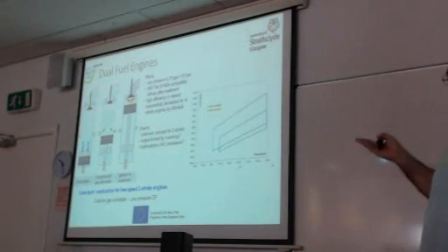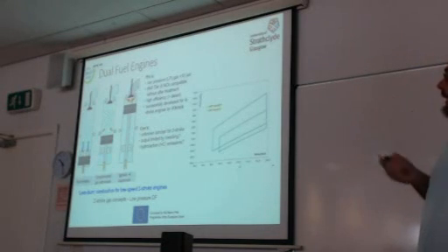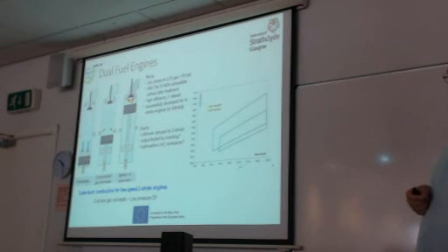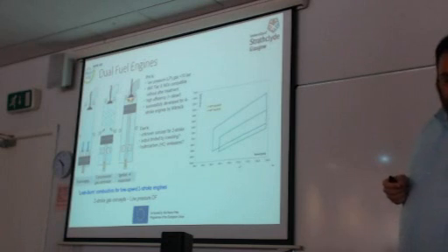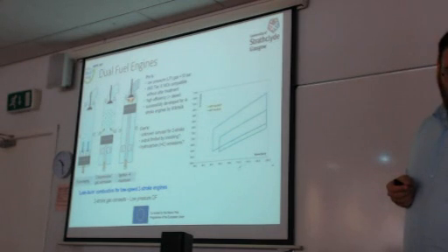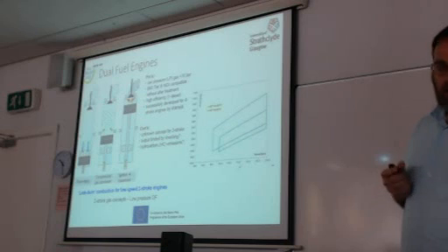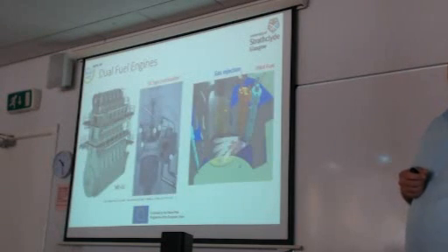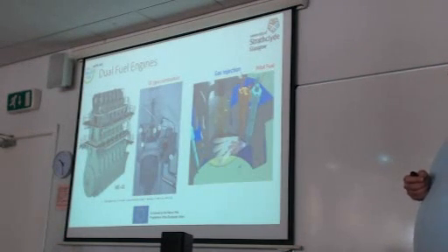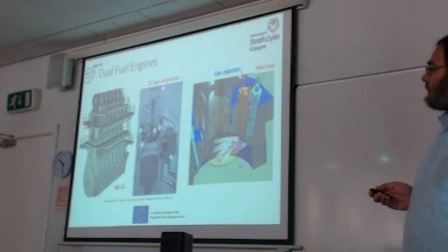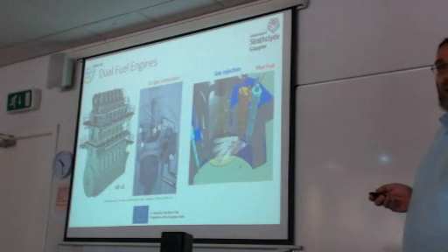Even in the case of a four-stroke diesel engine, in order to be converted into a dual fuel engine, a full conversion package is needed, which contains changing of engine components, injectors, the piping system, the feeding system, and so on and so forth. So it's not just that you have the fuel on board the ship and that's all. So you need, of course, an extensive conversion. Yes, but in this case you have to open holes on the block of the engine, and I suppose that is something complicated. Anyway, if you go to the site of Wärtsilä, you can find more information about that.